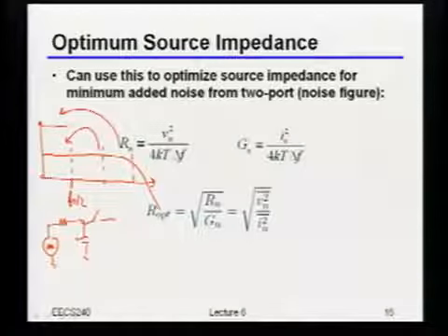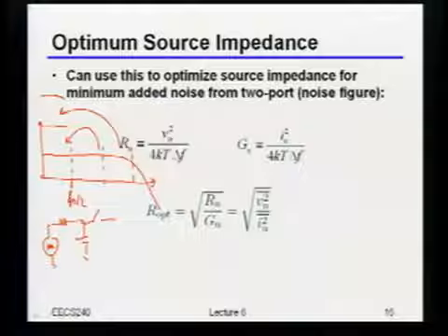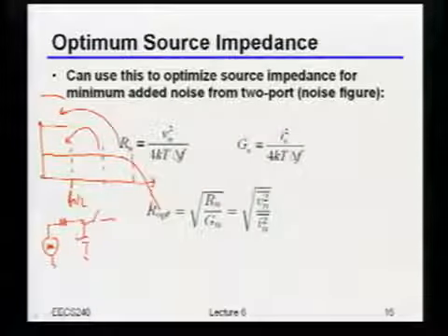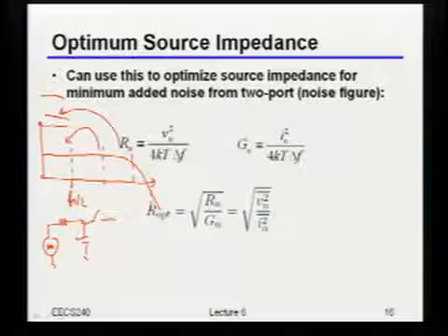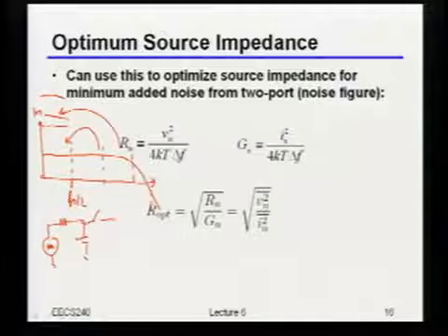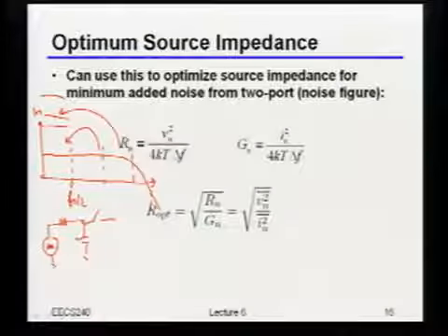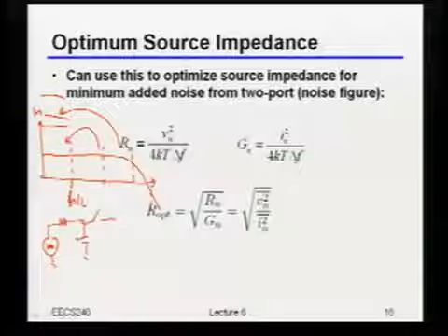But when I stack that, it's going to look pretty darn flat. And then by the time I get out over here, I've filtered so much of that already that maybe there's a little bit of curvature there, but the amount of noise I'm actually adding is pretty small. Because remember, this is a log. If it's in dB, that means it's a log scale on the top over there.